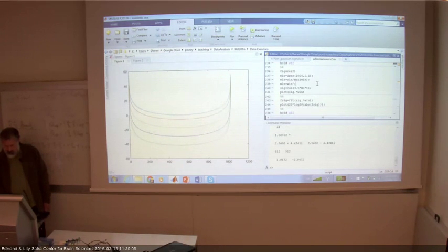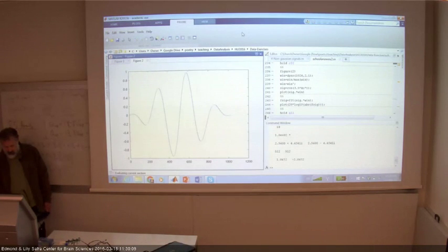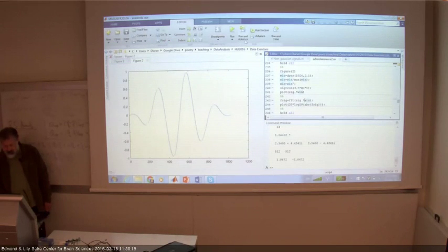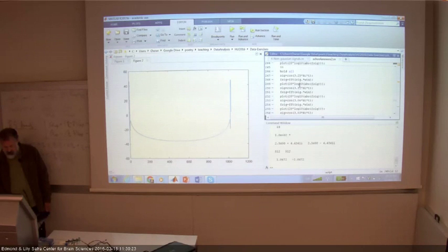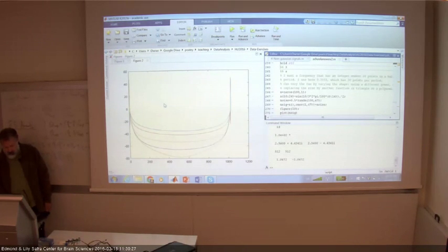Okay, and what I asked here is to use the DPSS window again, like we did. So this is a signal after I multiplied by the window and before I'm doing the FFT. And this is the FFT. Okay, and now I'm going to plot again all the other frequencies on top of it.